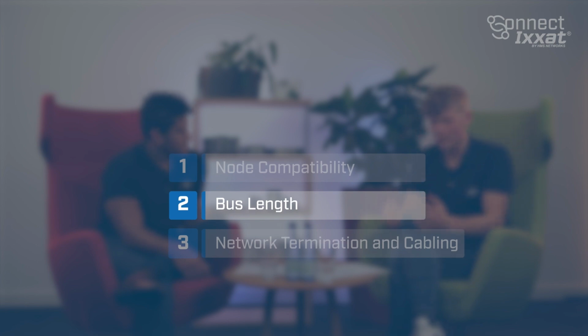The second one, and we touched on this also very shortly, is the bus length. So it is really difficult to name a rule of thumb here, because CAN in Automation, the CiA, so that's the big organization above CAN, they don't really specify a rule of thumb either. Actually, from a technical point of view, in theory, CAN-FD and CAN should have similar bus lengths, and we can say that in very clean line topologies without a lot of electromagnetic noise and with good cabling, this is almost true. So in these environments we see very good performance in terms of the absolute length.